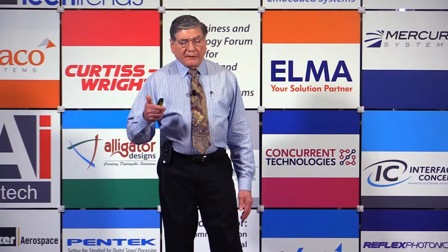So, I mean, that's one way of doing it, but this is completely opposite of our approach. So what we do is we put in all of the standard architecture that customers need in most applications for software radio, for radar, and so forth. So we have acquisition engines for like radar range gates, we have down converters, we have real-time power meters, we have time stamping, and then the DMA controllers help us move the data from our board into your system memory